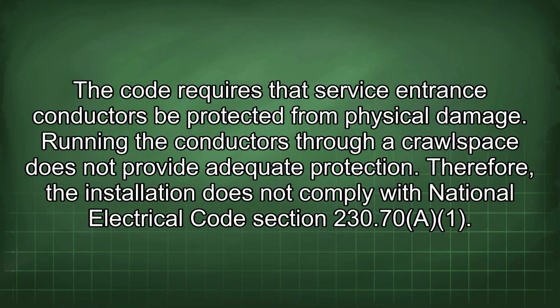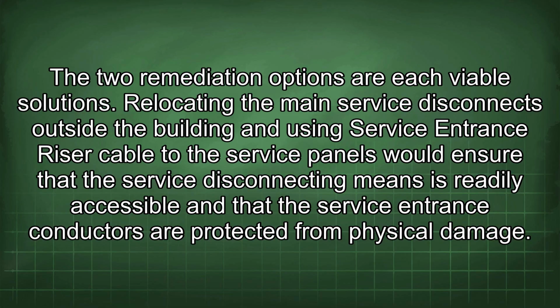The code requires that service entrance conductors be protected from physical damage. Running the conductors through a crawl space does not provide adequate protection. Therefore, the installation does not comply with National Electrical Code Section 230.70. The two remediation options are each viable solutions.